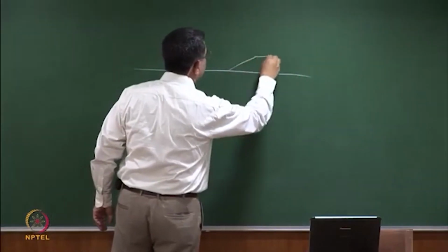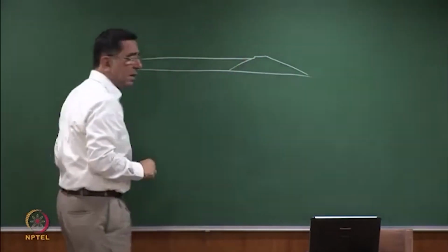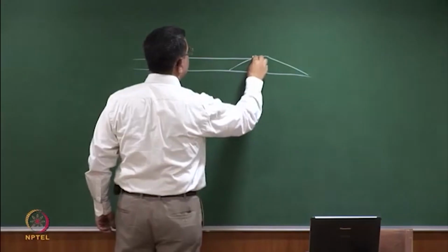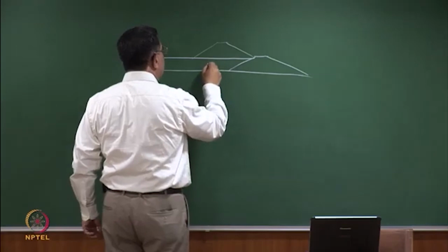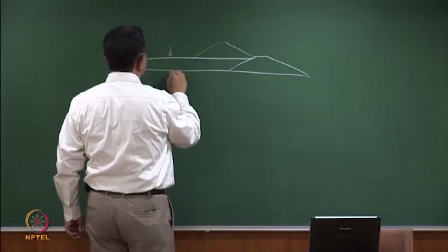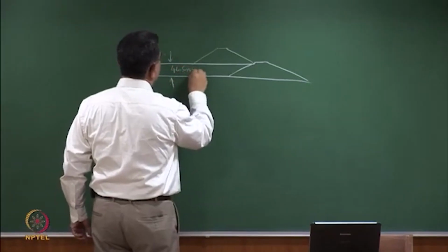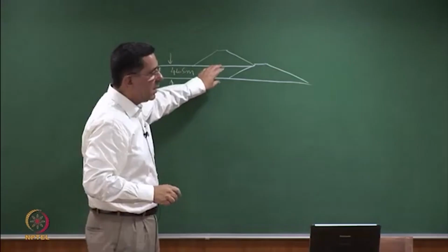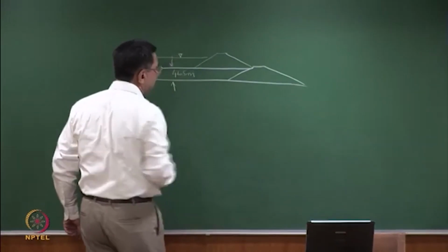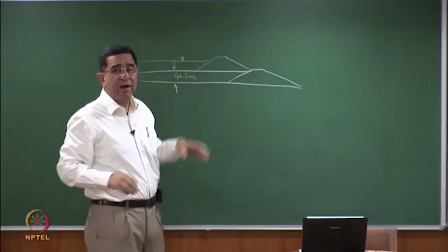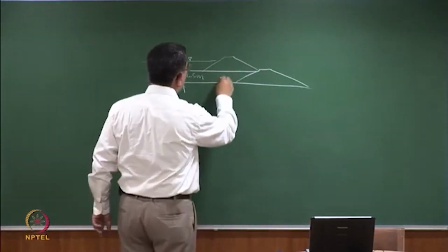So if I was to say, all right, this is my starter dike, and I have filled up my material up to this level. I want to make my next dike. Let me say I'm making it here. Now, can I compact this? This is, let us say, starter dike was 4 to 5 meters high. I am placing this on, because later on, as you fill up, the slurry level will rise. So you're on saturated, loose, hydraulically deposited material in the upstream. So the question is, can you compact this? How do you densify?